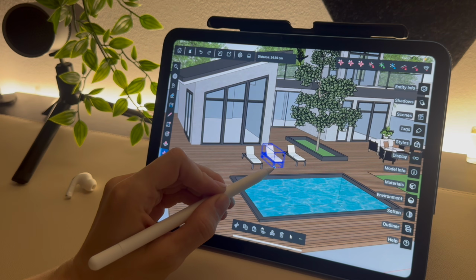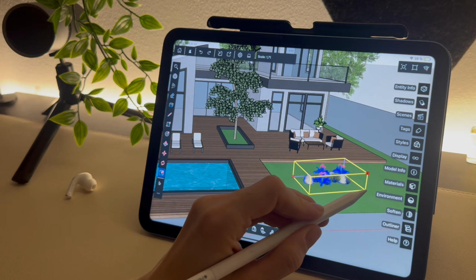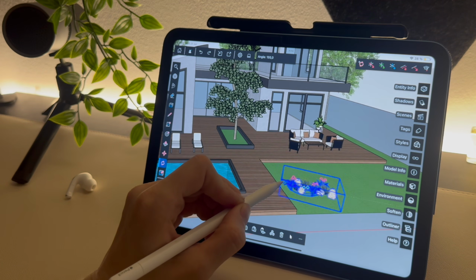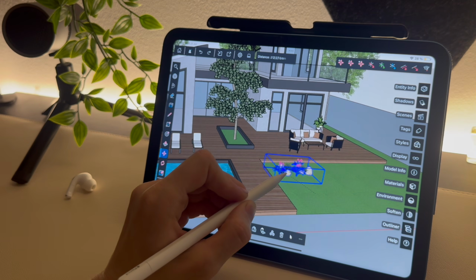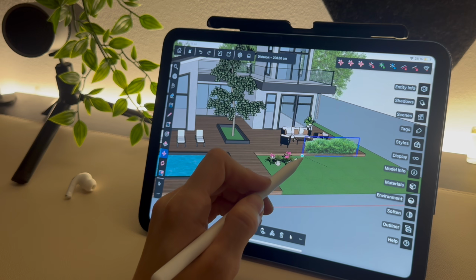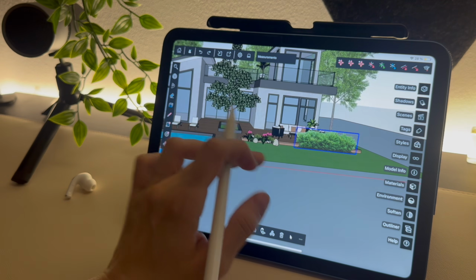By the way, be careful about the things you download from the 3D warehouse because some of the files are too big and they can slow down your 3D model, especially trees and plants. They just take too much space. As an alternative, sometimes you can find 2D plants like this one that also does the job, or you can add your own images of plants and trees.